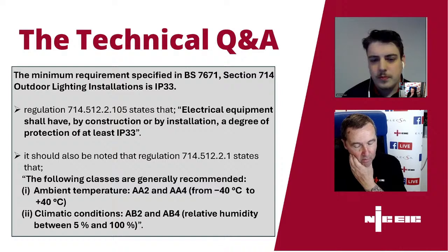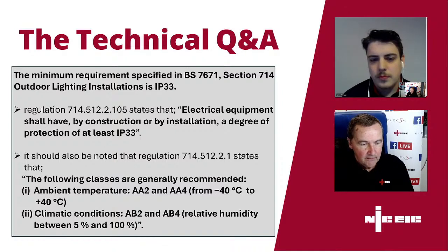Okay, so again, quite a common question we get. The 0.35 figure for TNCS and 0.8 for TNS are quoted as typical values that we can use when the supply isn't there yet, so we can use them when we're doing our design calculations. But ultimately the DNO don't have to achieve those values, so perhaps, as in this instance, they've got a TNCS where the Ze is 0.46. It's higher than the 0.35, but they're not going to do anything about it.